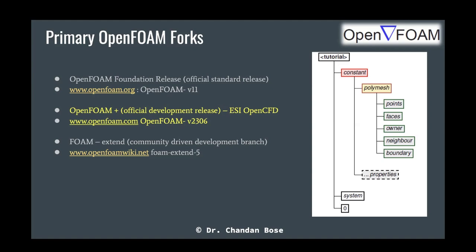Okay. Now I will come to the second session. If you want to move your body, for example for a fluid structure interaction problem, you need a dynamic mesh motion strategy. And for that, there will be another file within this constant folder, which will be called dynamicMeshDict. Okay, so it will be a dictionary file which will declare what type of dynamic mesh motion you want to use.